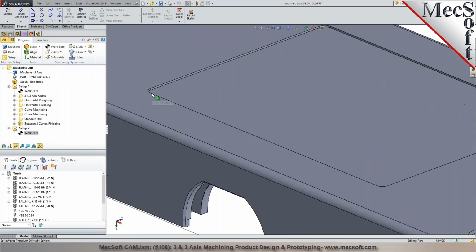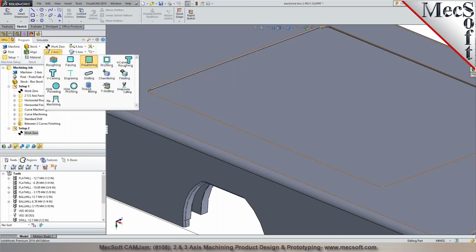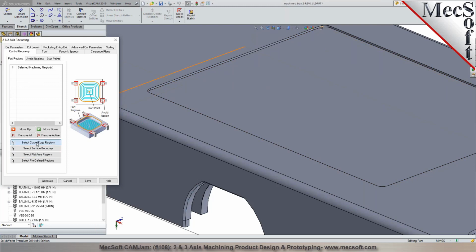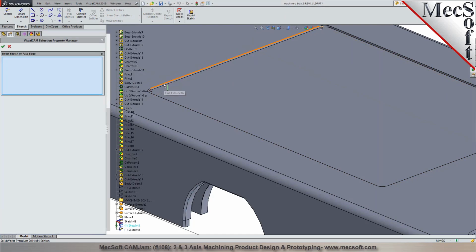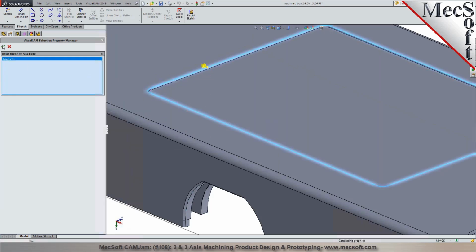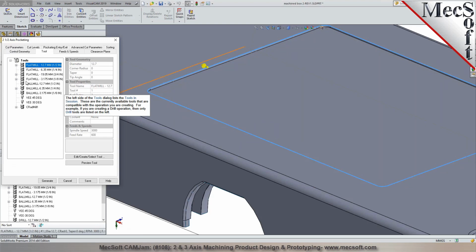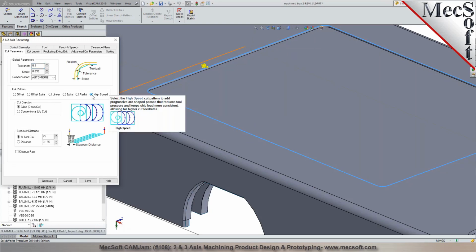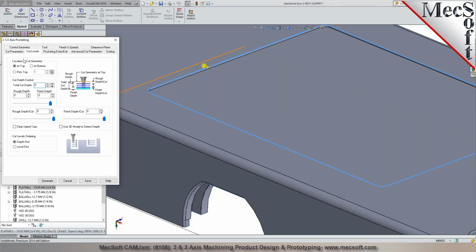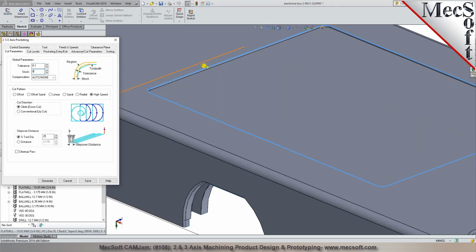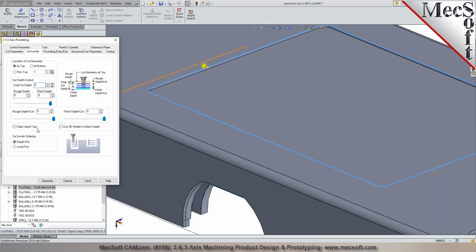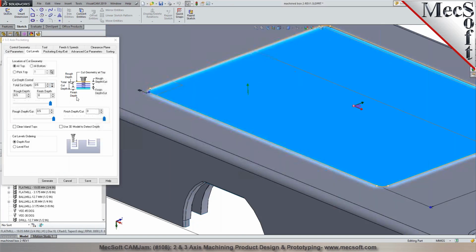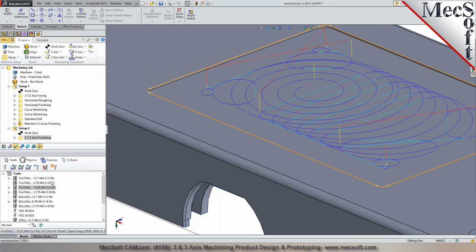And now I want to do this pocket in here. I could use 2-axis pocket machining, since it's prismatic, there's no drafts in there. I can right-click and say select loop, so pick the entire loop around the part. Grab a tool for it. I could just use my 3/4 mill. Specify the cut pattern, cut levels. You can specify if you want to leave any side stock. You can do that. And in the cut levels, you could say determine the depth using the 3D model, or you can even say just pick the top face and the floor. That's a 0.5 millimeter. Generate.